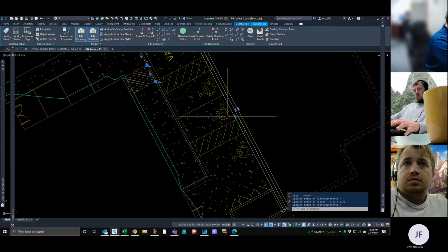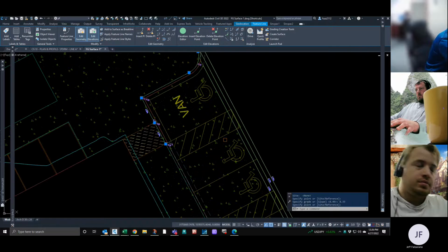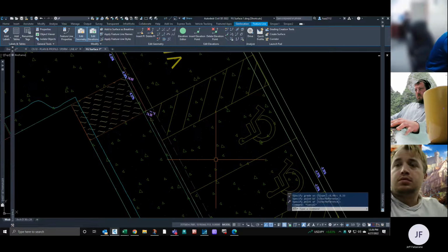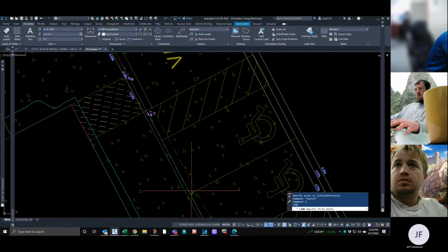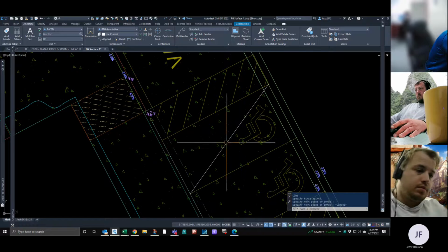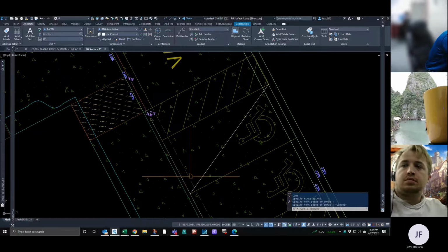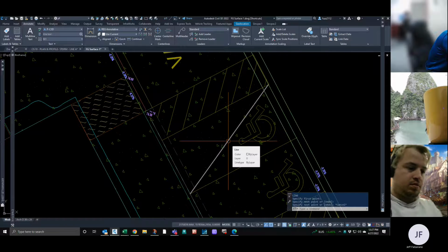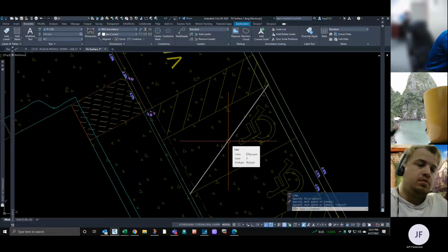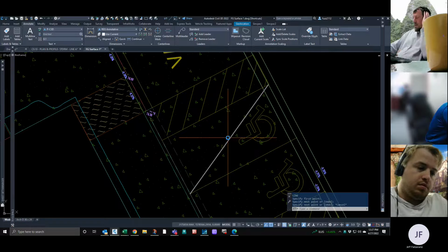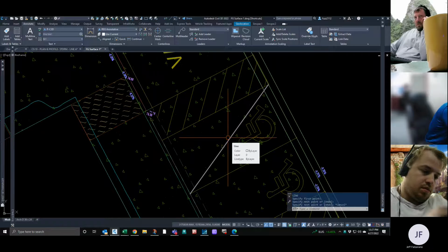Lengthwise and widthwise. So you're saying ADA spaces are 1.5 in each direction, max? Yeah, it just can't be over 2% diagonally. So 1.5 and 1.5. Anything over 2 going diagonally won't comply. Like 2.083333. Say that again. Isn't the max grade like 2.0833?